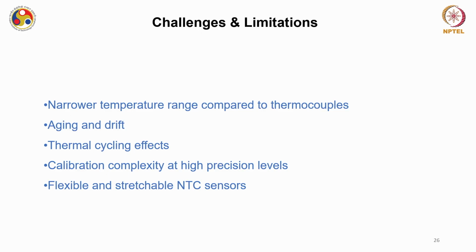And nowadays when you are talking about flexible sensors and other kinds of wearable devices, the development of flexible and stretchable NTC sensors is of great interest, and there are various challenges posed on that front, particularly associated with the semiconductor ink that has to be printed by current existing technologies like, say, inkjet printer or plasma jet printer technologies.